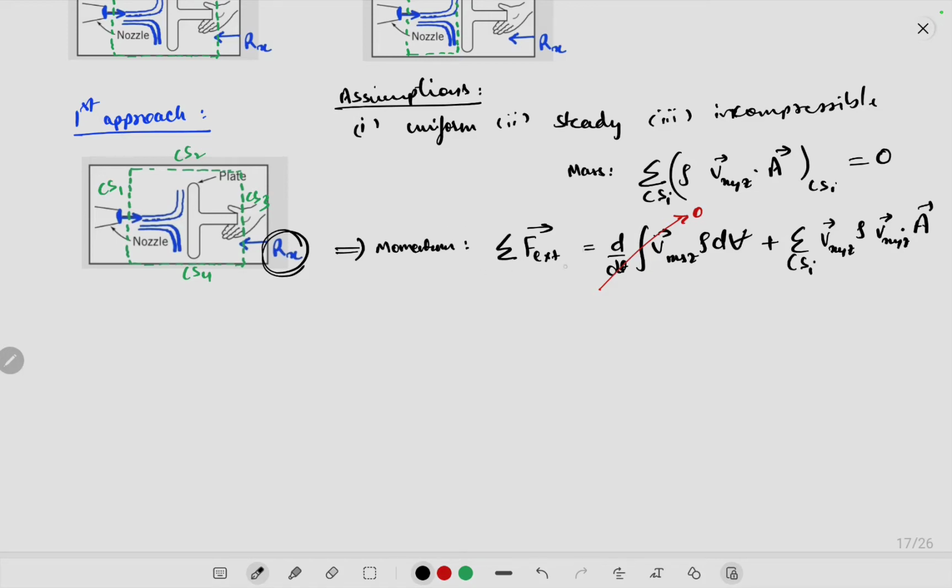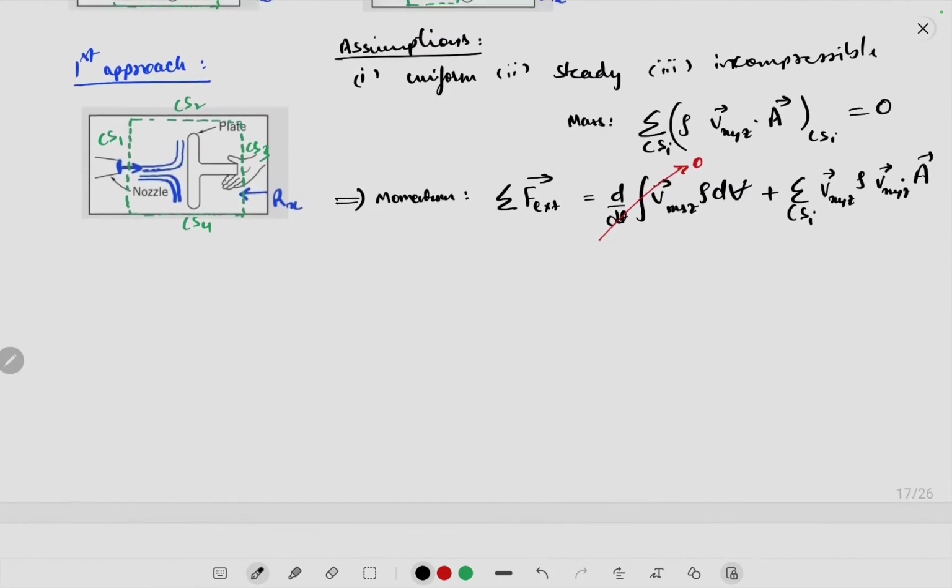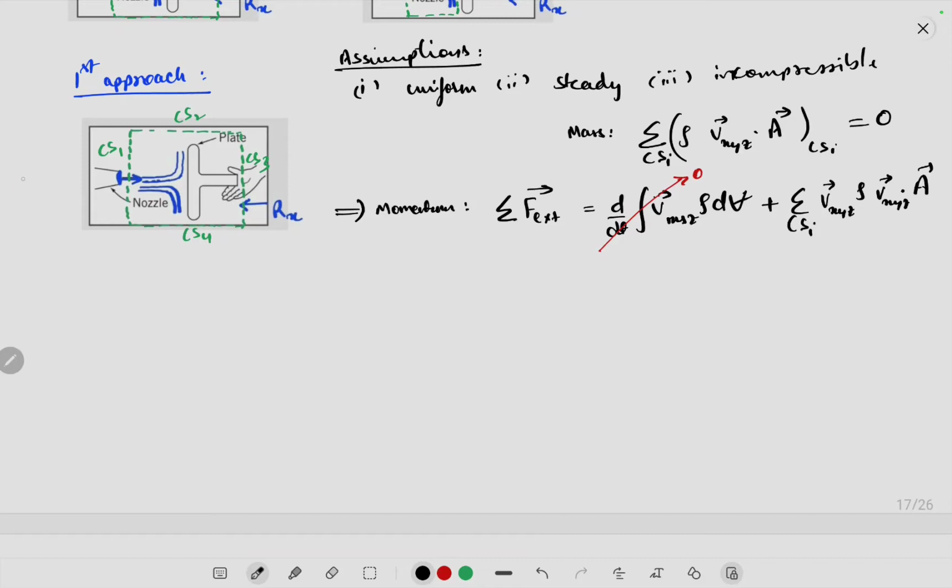Now let's take this equation, since we are required to find the horizontal force Rx. So if you see here carefully, it is written you have to find the horizontal force, okay. So since you have to find the horizontal force, let's just consider, so let's say this is x, let's say this is y, let's just consider the problem in x-axis only, okay.